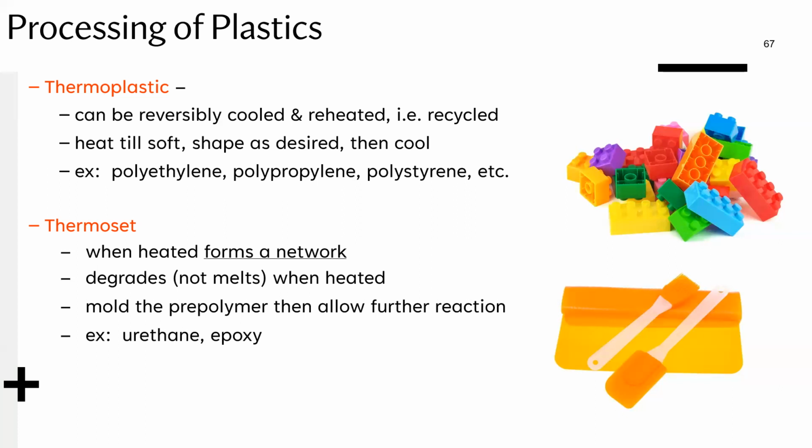If you cross-link it, similar to a lot of these materials that we mentioned, the epoxies and resins, similar to these light curable resins, for instance in nail cure when you have an acrylic material, or in your teeth where you use light to cure the filler, there's no way to remove that just by heating it up. These materials are permanently cross-linked, so if you really want to destroy it, you have to dissolve it with a solvent. In other words, what you're doing is destroying it, degrading it.